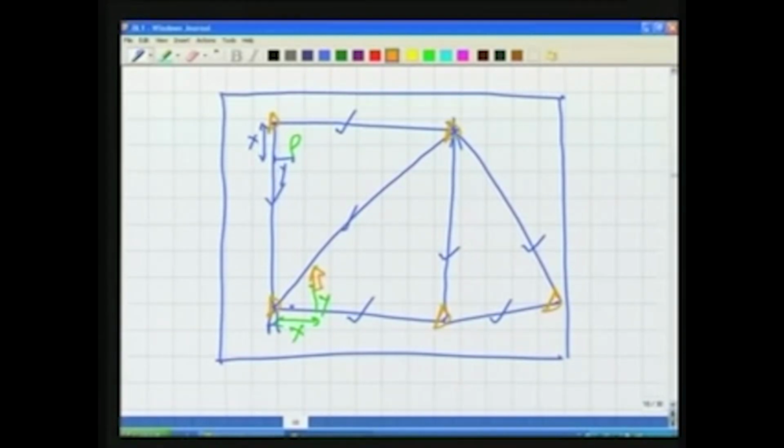Now, after that, even if we are slightly careless in measuring this y, it does not matter because it is not going to affect the plotting of this house, because these are two different things. The plot of the house or maybe plot of any other tree here, which we are plotting by measuring the distance here and this distance. So, we can say x here and y here. So, by this I can plot this tree. Again, this is an independent plot. So, this particular plot does not affect at all the accuracy of this plot.